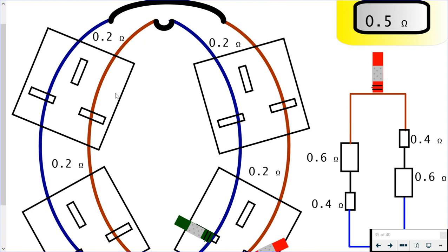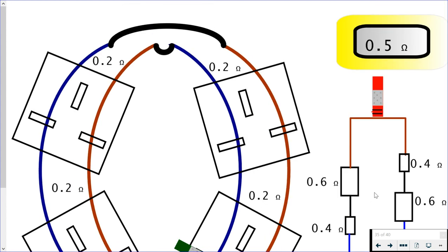So this side here, the loop length decreases. You'll see there we have this accumulated 1 ohm, the sum of these two resistances either side is 1 ohm. If you know anything about parallel circuit calculations, again, we still have the same resistance either side, 1 ohm and 1 ohm. Our calculated value is 0.5 of an ohm.